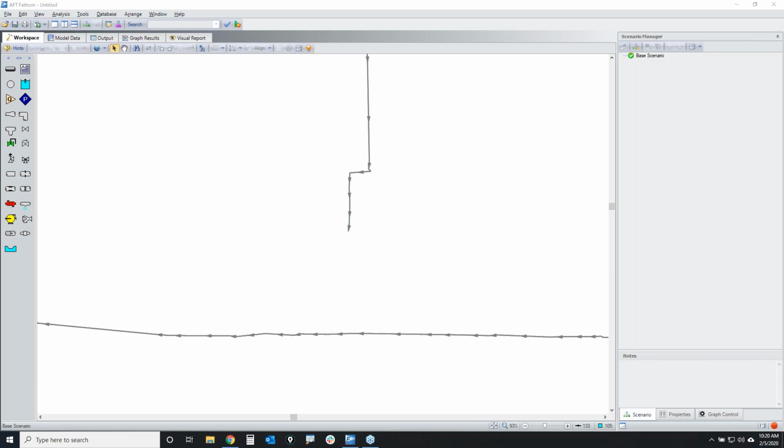And so here's the conundrum. Is the end of this pipe just dumping out into the atmosphere, or is it actually supposed to be connected to this particular pipe right there? Well, we don't know. So this is where your GIS team is going to have to do a bit better of a job to make sure that things are cleaned up for a flow model. In this particular system here, this is maybe a well pad where it's just dumping into that well pad right here, and it may not be connected to that pipe.